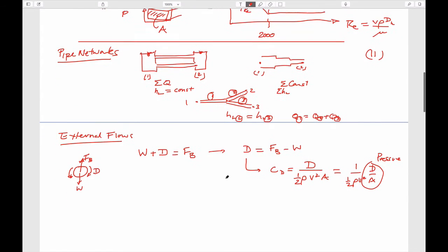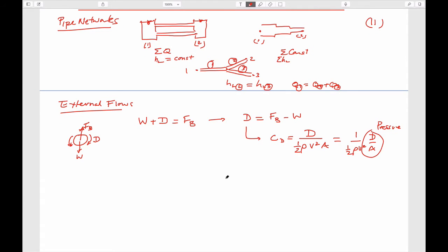And so typically what we end up doing is trying to solve in 2 particular ways: either for the laminar case or the turbulent case. So turbulent is easiest because you can just rearrange this in terms of a coefficient of drag, and you can resubstitute this term here into here, and you're left with an expression where the only component to solve for is the velocity.